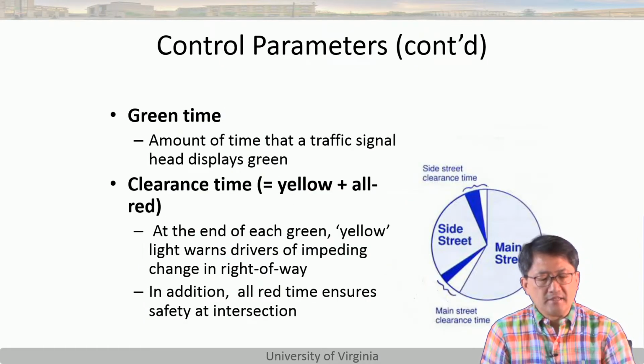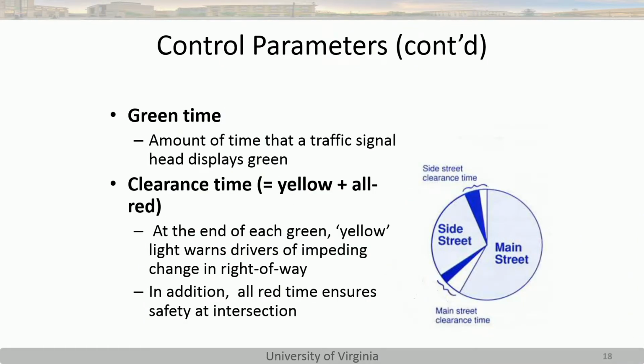Again, green times are easy. Yellow and then all red. Not sure, do you understand the all red time? It is not easy to observe, obviously. So when you have an end of green and we provide yellow, sometimes yellow is not long enough. This is for safety, obviously.